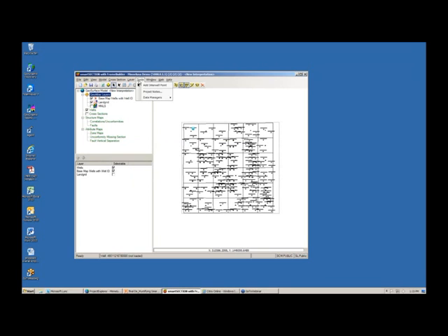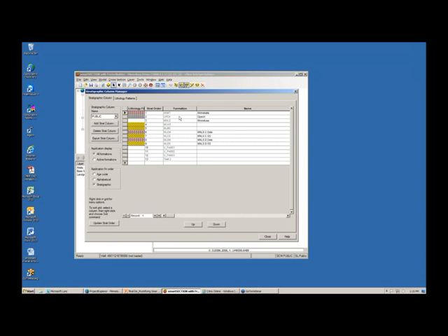Next, it's very important to establish the chronostratigraphic order of the formations that you're going to use. So you're going to go up to Tools, Data Managers, and get Strat Column Manager. You're probably all familiar with Strat Column Manager because it controls the formations that are displayed and utilized in Wellbase. What happens here is that smartSECTION uses algorithms and a geologic model that assumes that the younger formations are shallower than the older and deeper formations, and it bases all its modeling calculations on this assumption.